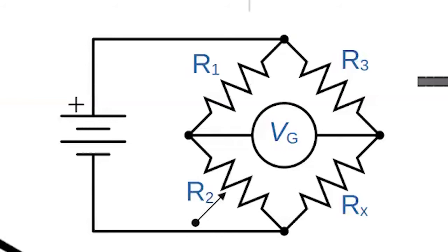If everything is balanced within the circuit, that voltage difference will be 0. However, if a weight is applied, such as a volume of liquid, then R sub x will change, yielding a different voltage difference. That resulting voltage difference will then be captured by the red box and sent over to the software. We will approximate the volume of liquid being applied on top of the load cell sensor.